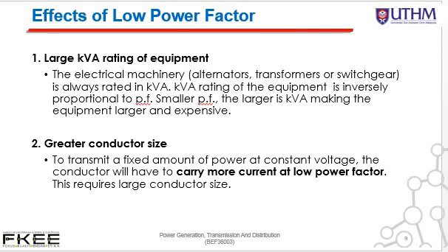It is clear that the kVA rating of the equipment is inversely proportional to the power factor. The smaller the power factor, the larger the kVA rating. Therefore, at low power factor, the kVA rating of the equipment has to be made more, making the equipment larger and expensive.